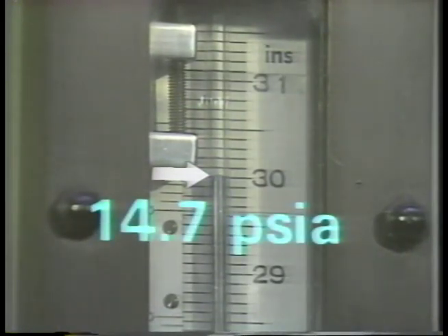We say that barometers are used to measure the atmospheric pressure, but a barometer actually reads inches of mercury, not pounds per square inch, which is how we usually express pressure. If you need to use a barometer reading to compensate other pressure readings for changes in atmospheric pressure, you'll need to be able to convert from inches of mercury to psi. For example, if there is low pressure, the barometer may drop and read 29 inches of mercury.